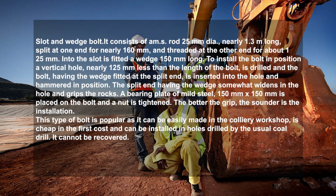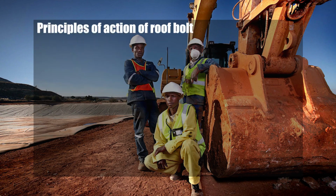A bearing plate of mild steel 150 mm by 150 mm is placed on the bolt and a nut is tightened. The better the grip, the sounder is the installation. This type of bolt is popular as it can be easily made in the colliery workshop, is cheap in first cost, and can be installed in holes drilled by the usual coal drill. It cannot be recovered. Principle of action of roof bolt.